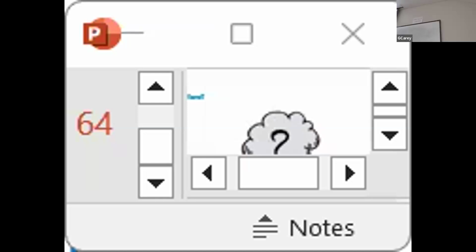So then you read this whole pump affinity law exercise we just went through: the flow rate, cut it in half, cut the speed in half. It's a 1-to-1 relationship. It works. Well, now I go back to that software and I say, I want to pick a variable speed pump, not a constant speed. So 100 gallons a minute at 100 feet of head.